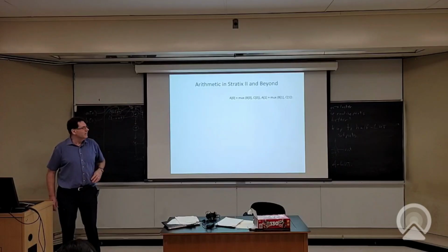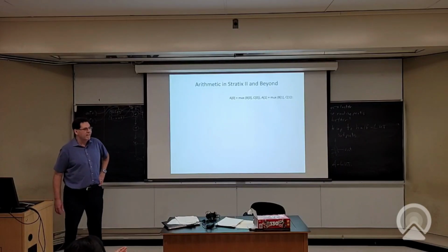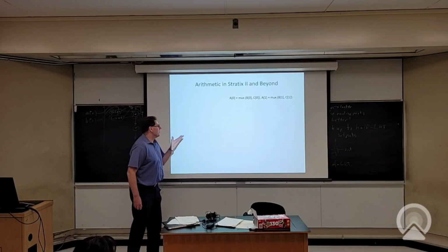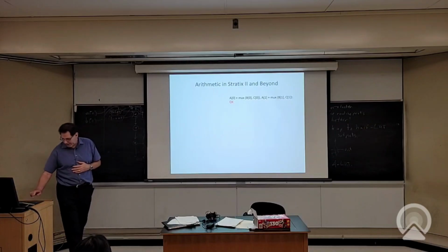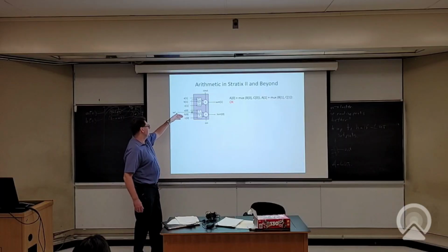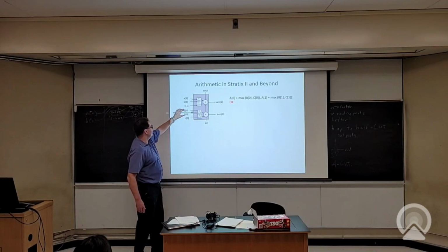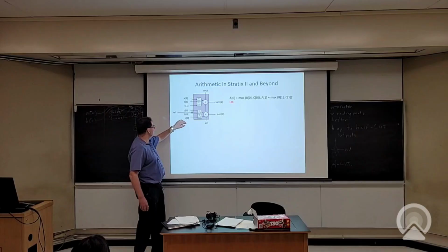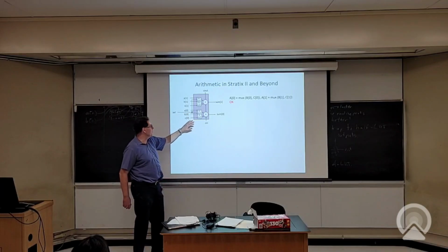It's like if it's a fractional 6 LUT, like the 2 extra. Yeah, so this one is fun. So the way you look at it is, what have I done here? A or B. I need to fix this figure. What I actually did is A or B muxed plus C. So I just flipped the variables, but you get the idea. I'll fix it afterwards. I'll eat a chocolate bar for finding my own mistake.